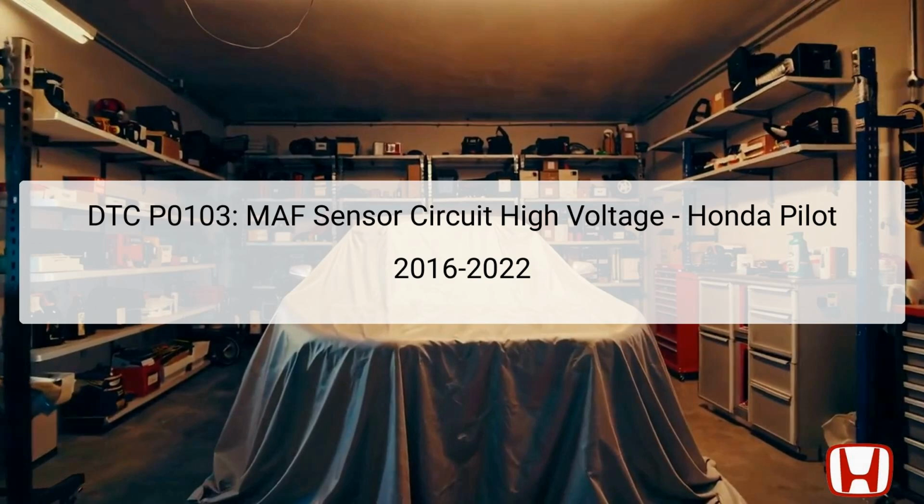The MAF sensor plays a critical role in measuring the amount of air entering the engine, which is vital for optimal fuel injection and engine performance. A high voltage reading from the MAF sensor can lead to engine performance problems, increased emissions, and reduced fuel efficiency. Addressing this DTC properly will help in ensuring that the engine operates efficiently and meets performance standards.